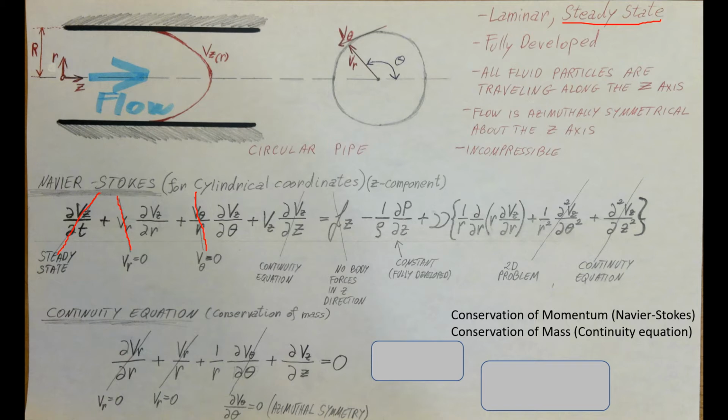And just like we discussed, one-dimensional flow, Vr is 0, therefore these cancel out, and we have a symmetry around this z-axis. We have azimuthal symmetry, or I hope that's how you say that word. It's quite challenging for me, but that's what it is, right?